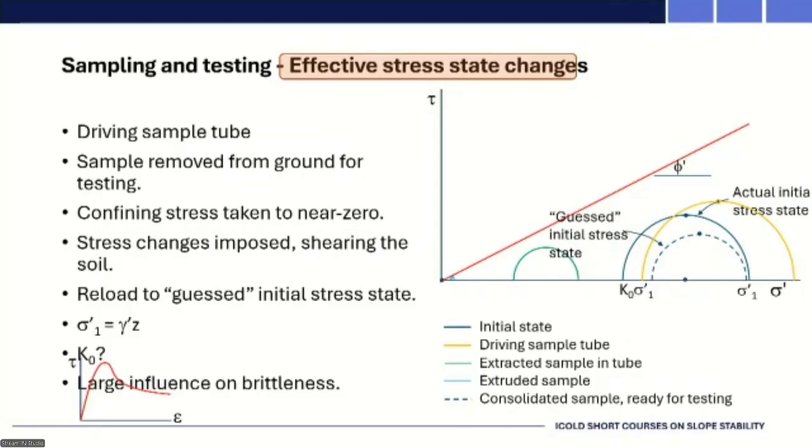When it is sitting at that stress state very close to the origin, it is very, very prone to be damaged, because you can imagine a small amount of load that you apply to the vertical or the horizontal stress on the sample will very quickly enlarge that Mohr circle to violate the failure criterion, and you will plastically deform the sample. So if you manage not to do that, you can then raise your cell pressure and take the sample back to a stress state where we thought it would have been, where we thought it was going to be at the dotted circle that I showed.